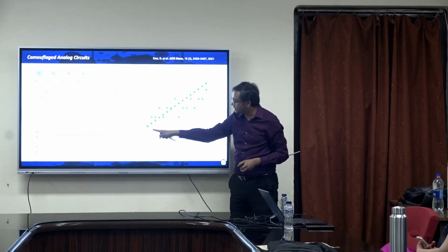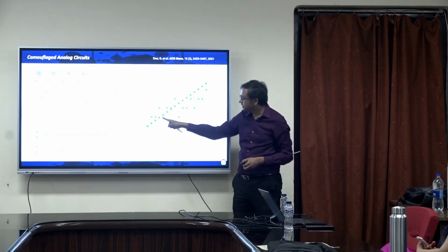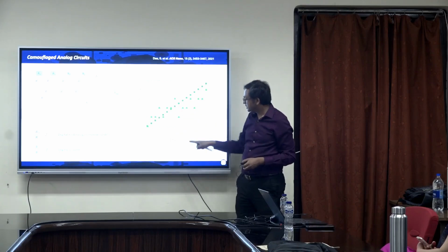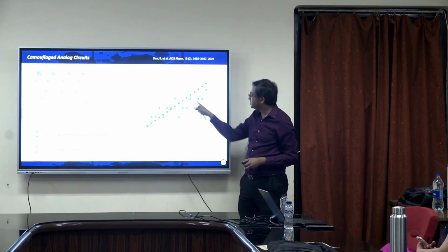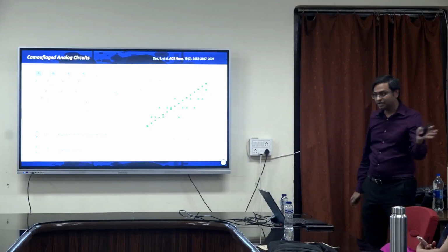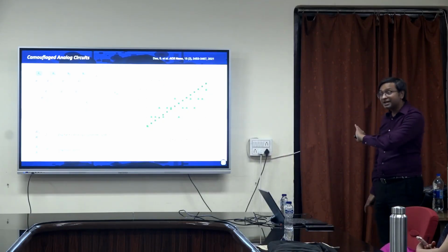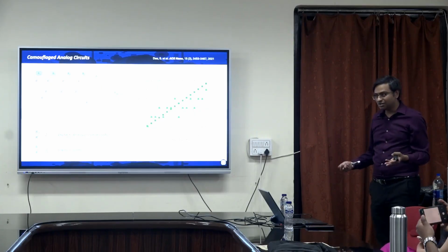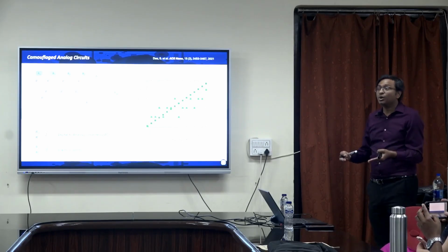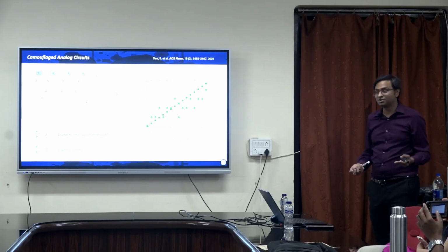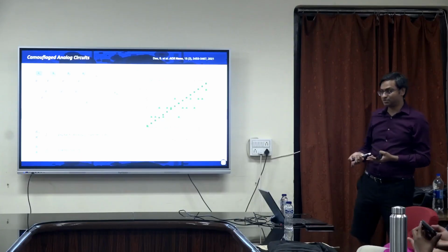Whenever you have one 1 in the sequence, it will be 1. If you have two 1s, then it increases. All the two 1s go here. If you have three 1s, then they are here, and all the four 1s. The counter: how many 1s are there in your bit sequence? So the functionality is completely changed, right? Without changing the circuit architecture, which is vulnerable to reverse engineering. You see, and what are we using? A very unique property of this 2D material.